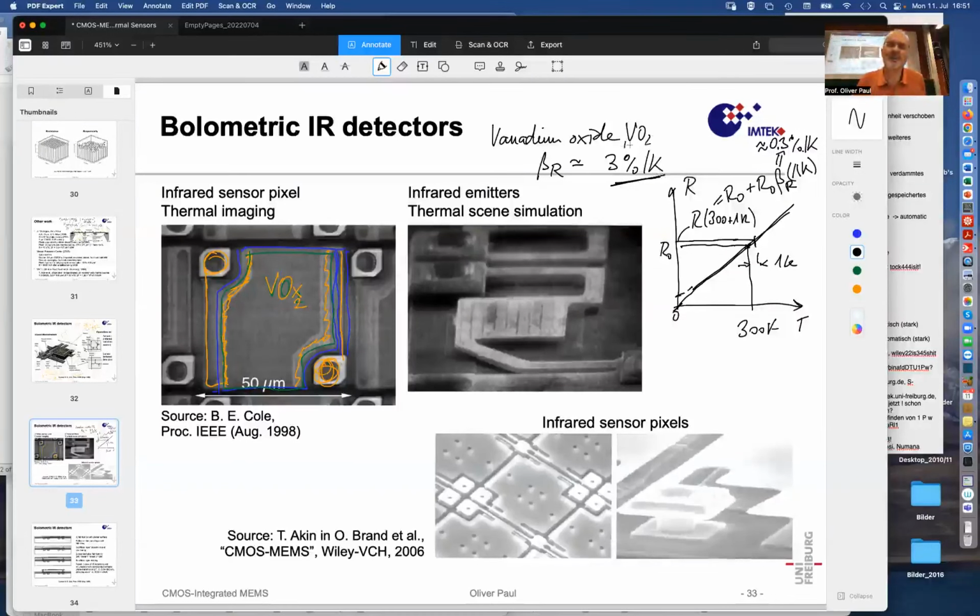And the reason is that this is not just a normal metal, it's an oxide that expands, that has a thermal property, that the band gap, it's almost an insulator. It's not really a semiconductor. It's more conductive than a semiconductor, but it's at the brink of becoming a semiconductor, and that makes a huge temperature coefficient of resistance. Actually, the phenomenon that occurs here is that of a so-called Mott transition.